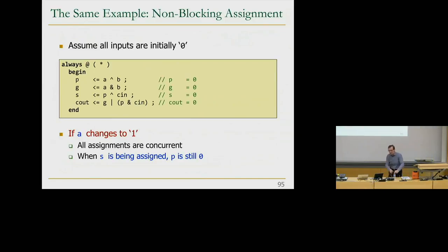Yes? When you say they are executed concurrently, could it be that a statement that executes concurrently will get translated into components which are slower compared to the other ones, and then the new value has already been assigned? We'll talk about timing later, but a good synthesis tool should not do that in this case. Basically, it should ensure that these are done at the end. But yes, there could be dangers over here. Let's talk about timing tomorrow. So logically, all of the values should be changed at the end.